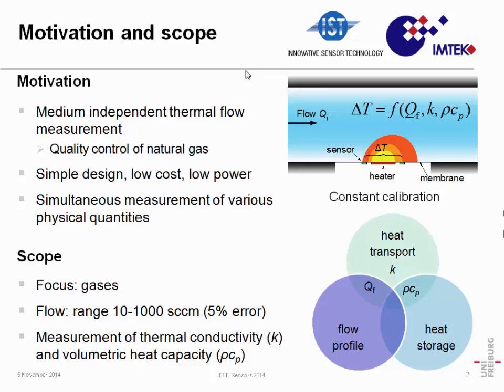upstream and downstream. This temperature difference usually depends not only on the flow rate inside the channel, but it also depends on the thermal volumetric heat capacity and the thermal conductivity. So the main focus of this work is to determine those two parameters in order to recalibrate the reading that you have on the temperature difference, in order to get the flow rate.